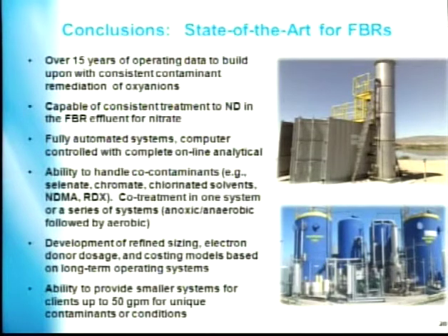But within the same reactor, you can treat things like selenate, chromate, as well as nitrate and perchlorate. And we have data to show that. We just completed a study with Kennedy Jenks consultants at the City of Davis, demonstrating the applicability of chromate treatment with the new MCL coming out, our draft MCL coming out from the DPH. And then we've really developed and refined the sizing and the electron donor dosage.